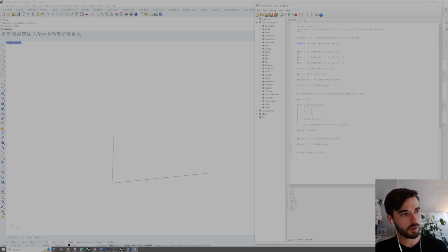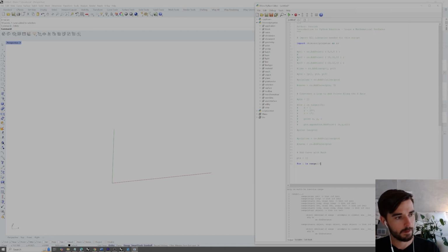This will just be a simple one, but we want basically that same structure. So we want an empty list saved as points. We want a range, or a loop rather. So we can just use, for i in range 10. We want some x, y, and z variables, and we want to make points and then use those x, y, and z variables to actually do the point construction, and then we can add each one of those to our points list.